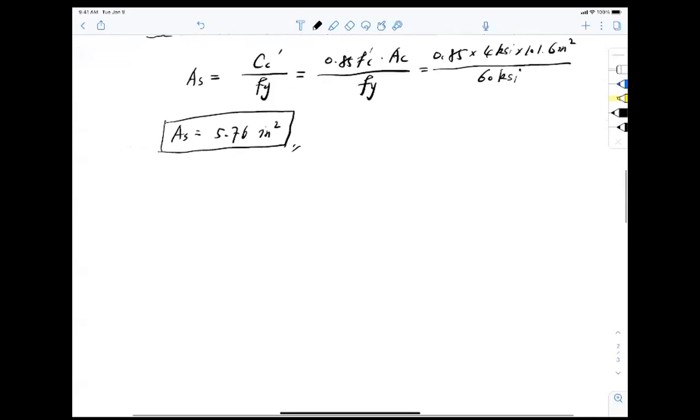So that, ladies and gentlemen, is my first estimation of reinforcement needed for this irregular section. Just an estimation, right? It's not finalized yet. So with this, I say that if I have magical fingers, I can select any bars I want. And somewhere, somewhat, magically, let's just say I can provide an accurate AS, which is unheard of in the field, but let's just say I can provide that to make our life easier for this problem. Then what happens?